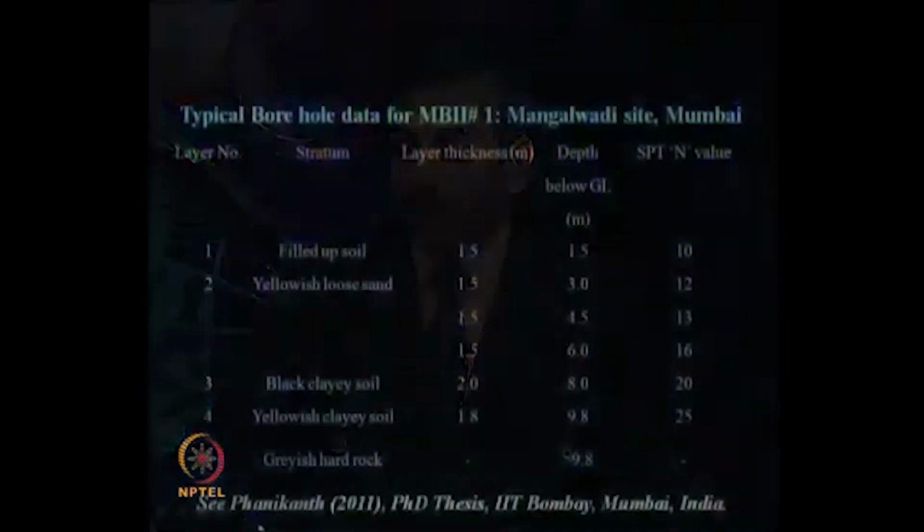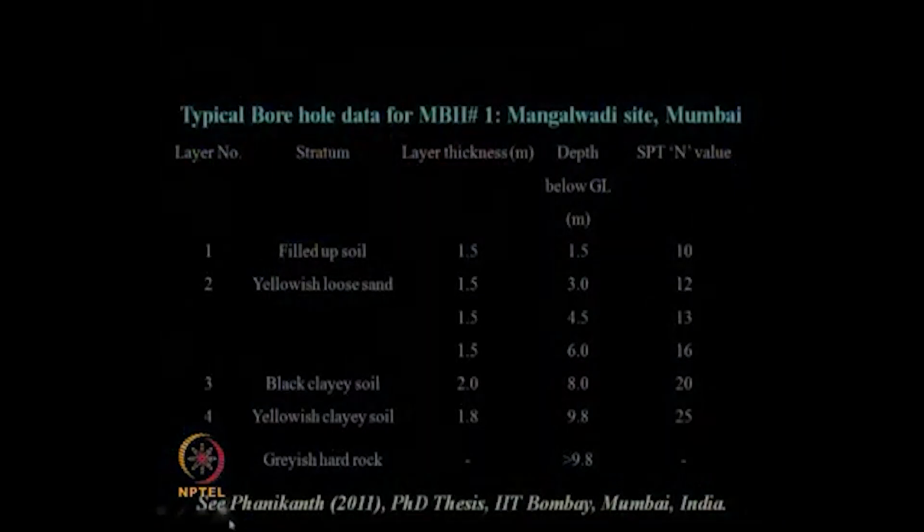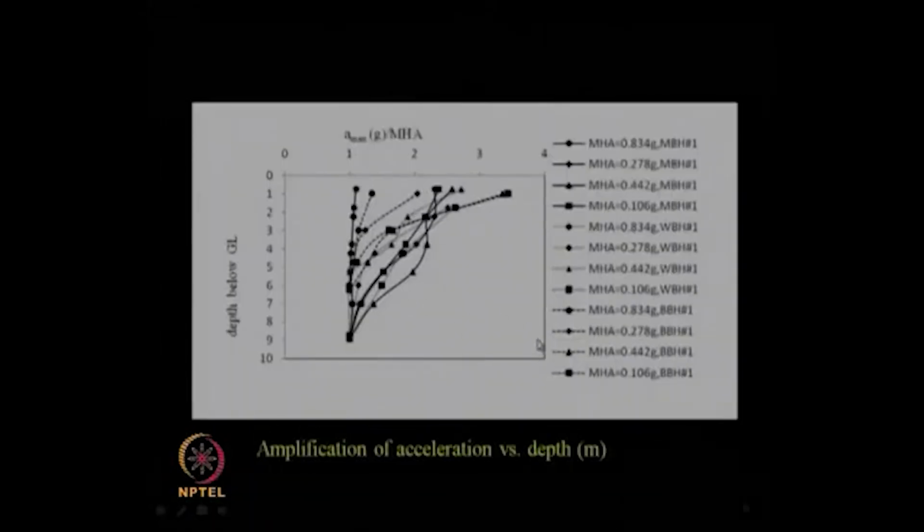For that, I referred in our previous lecture itself to the PhD thesis by Dr. V.S. Phanikanth, 2011 at IIT Bombay. He did his PhD under my supervision. Initially he carried out the ground response analysis for various soil sites in Mumbai city. This is the Mangalwadi soil site, borehole number 1, with typical soil input data taken from the borehole data. It has been used under different earthquake loading conditions with different input motions like Kobe, Loma Prieta and Bhuj earthquake motions.